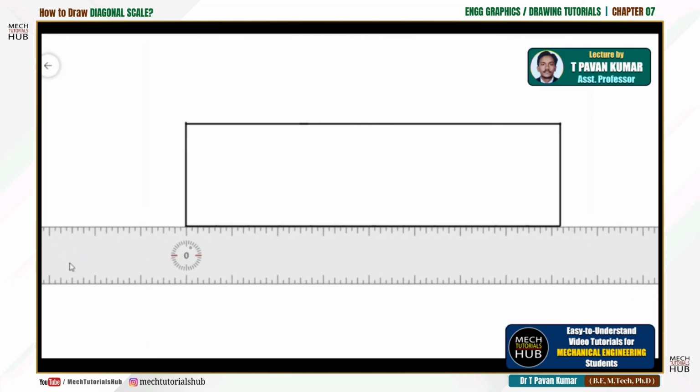Okay, so what I try here is we can simply divide at every 2 centimeters to make it 6 different parts, or else you can draw an acute angle and divide that line into a number of segments, and join the last end point with the corner of the scale. Accordingly, draw the parallel lines to get it. Now here I'll just divide by going through the divisions, meaning every 2 centimeters. This is 1 up to 3. So every 6 divisions I'll consider as 2 centimeters.